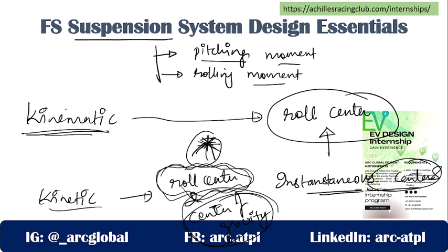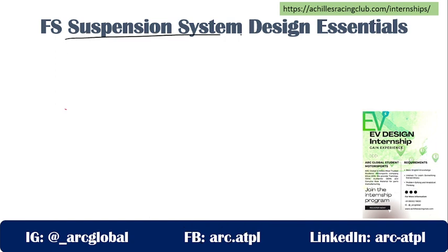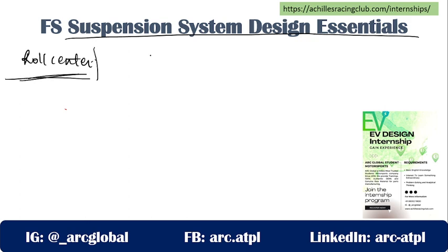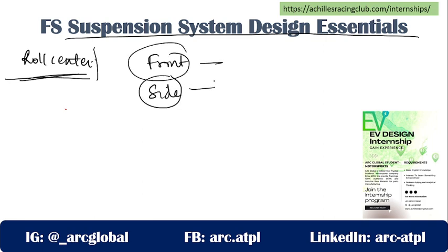So if you have been given the target to design the suspension system for your vehicle, my dear friends, the first thing you need to focus on is determining the roll center for your vehicle. What do we actually mean by roll center and how do we calculate it? If I look at my vehicle from the front, or from the side, in both ways I can find the roll centers of my vehicle, the swing centers about which my tires are moving up and down.